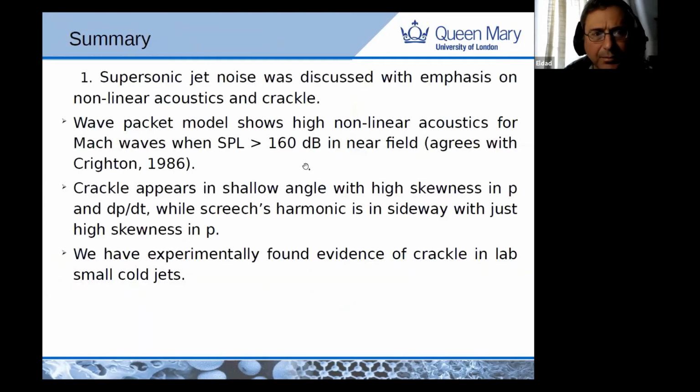So I will just summarize. There's been quite a lot of topics. I went flying through them. So the first thing I talked about was supersonic jet noise, and we looked at the wave packet, and we again verified what Crighton said in 1986, when we're getting the SPL inside at 160 dB.